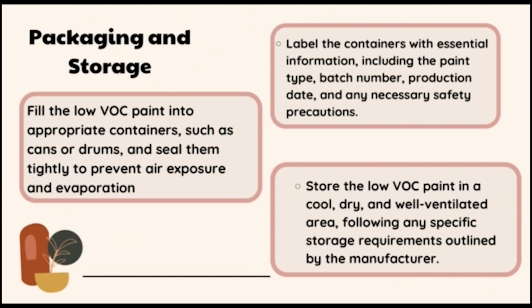Next we continue to the packaging and storage. So in the packaging and storage, we have to fill the low VOC paints into the appropriate containers such as cans or drums and seal them tightly to prevent air exposure and evaporation.